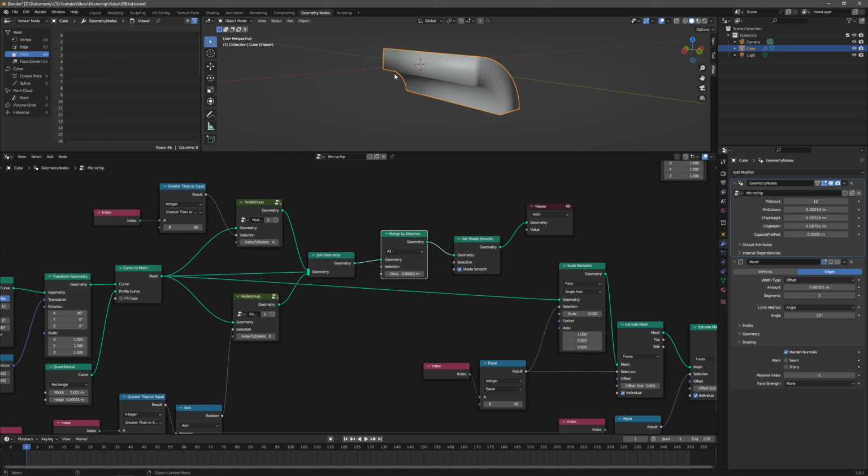Okay, the top face, we chose a correct index. We will notice it by the shading of it, because if you choose a wrong index of the face, you will see that the shading is flat here. So let's return to 0, and the bottom face is obviously wrong, so we have to change the deleted index to 1, and now the shading is working, I think, pretty well.